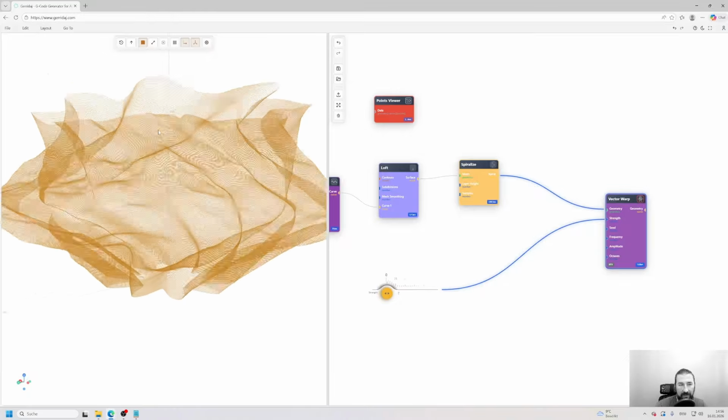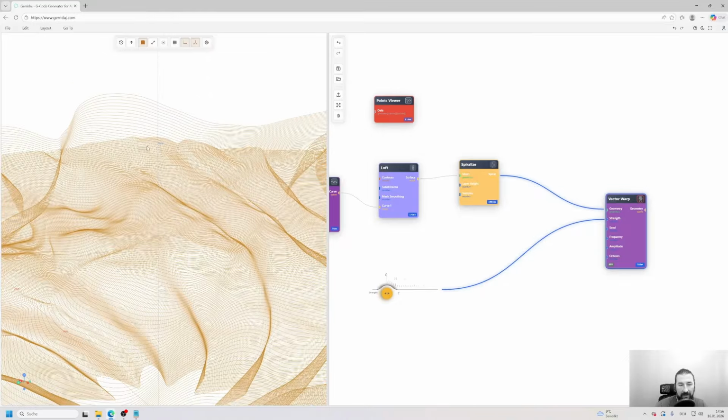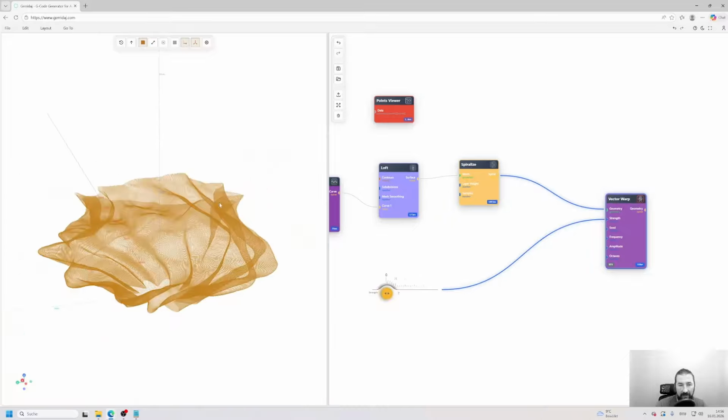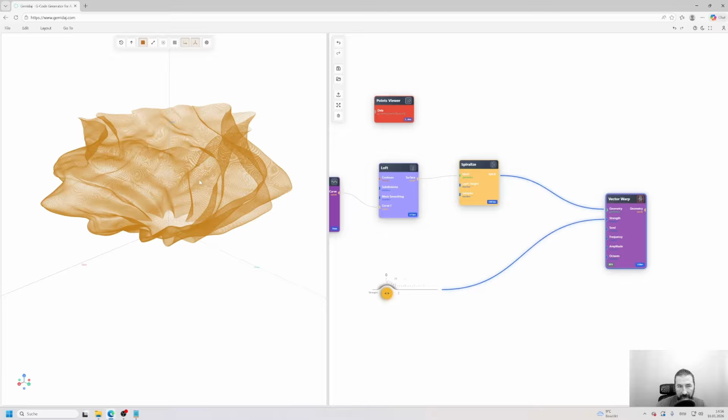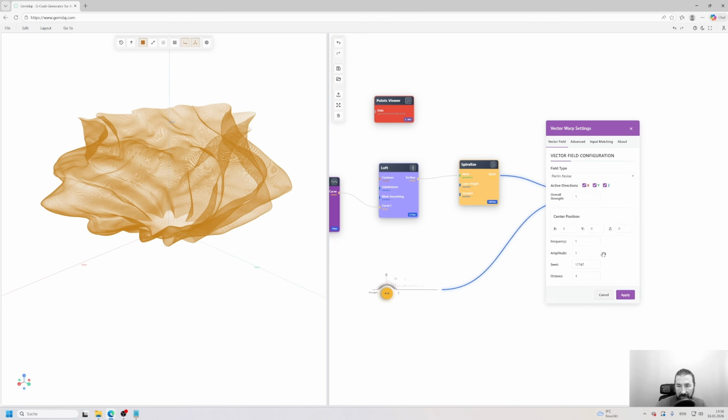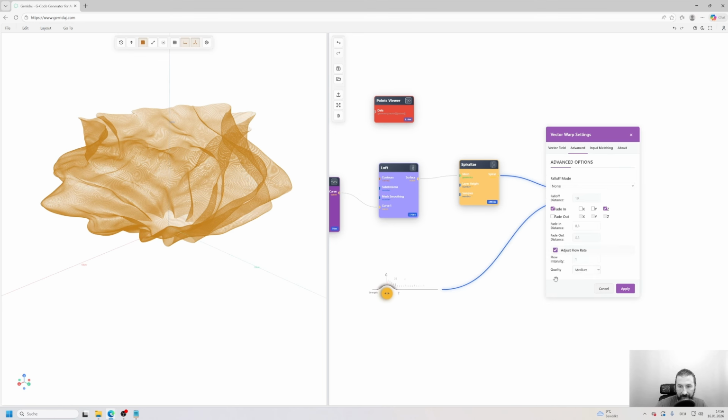And you see, in this case, you don't even need some compensation for different layer heights. What it does, you see, the distance between some layer lines is increasing, and the distance between others is decreasing. And if you print it with constant extrusion, you will end up with less extrusion in areas where it is further apart, and too much extrusion where the lines are squeezed too close together. And in this node, we have compensation for that.